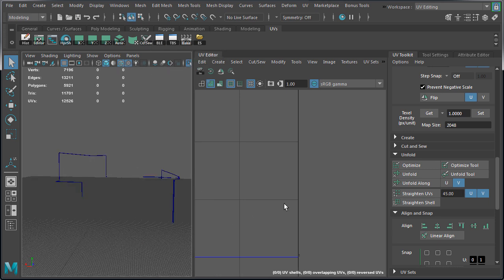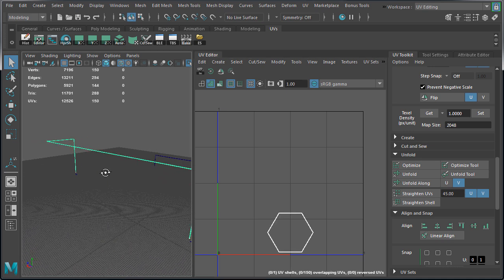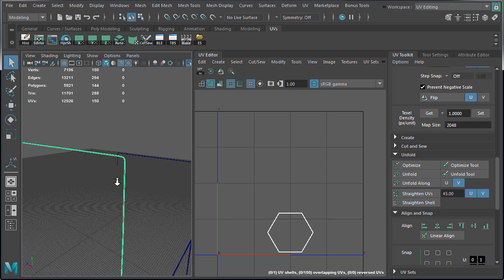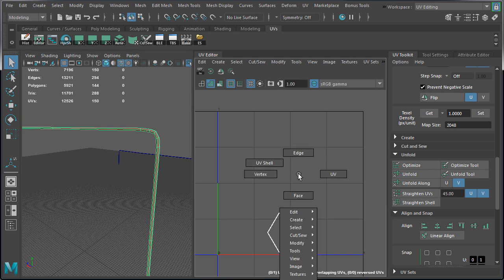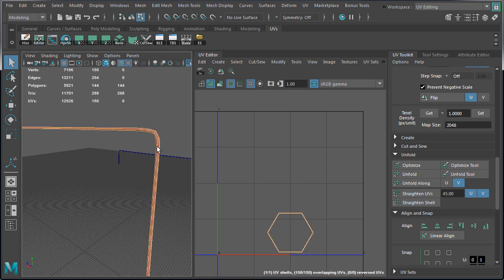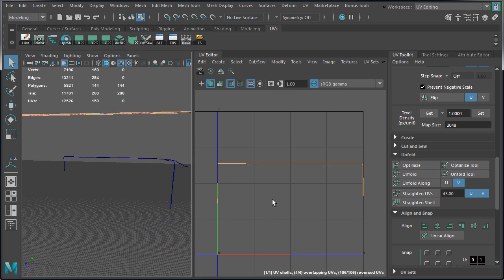And we're going to UV the largest wire first, so we'll get it out of the way. So let me run through the steps that we're going to use to UV every single wire. Select that wire, switch over to face component mode, and double click to select every single face. Then we want to project on X or Z. And in this case, for this wire, I'm going to project on X, but Z would also work.